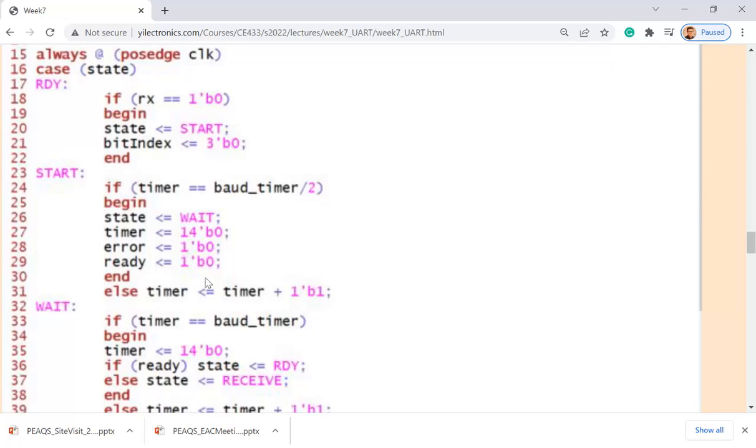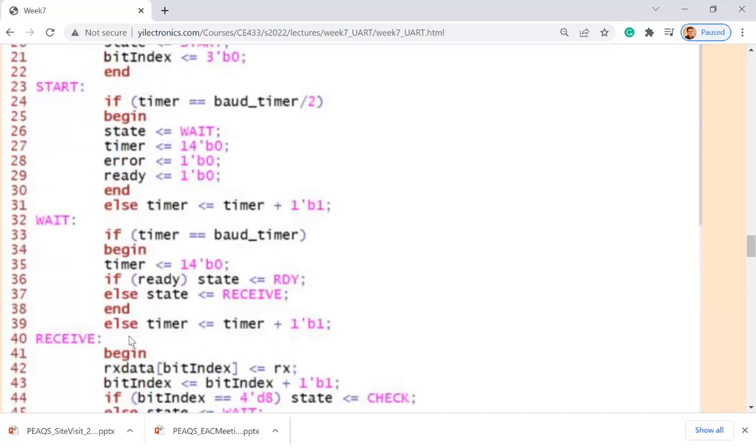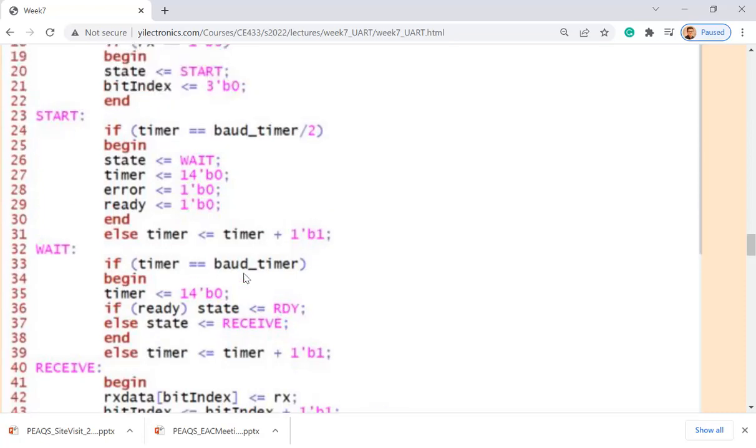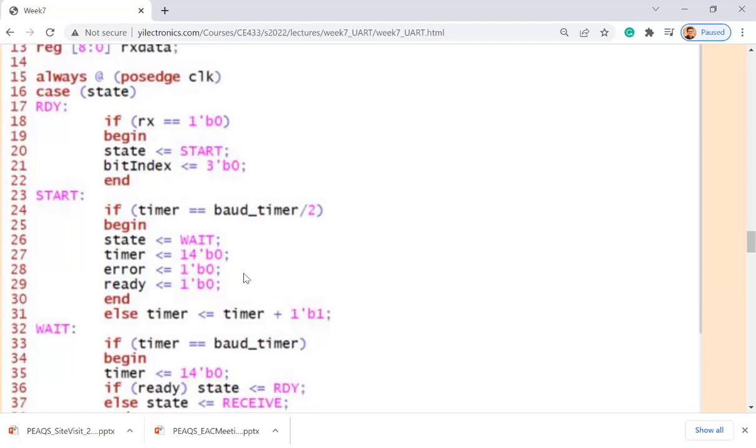And then it does these things, but still not saving any data to the bank. Just clearing out all the bytes or bits, like resetting everything. And then it gets into here, then you count to max again, and then start saving, start receiving the bits. Why is that? Whenever I get started, I receive the start bit. I know the next clock cycle is going to be the data, right?